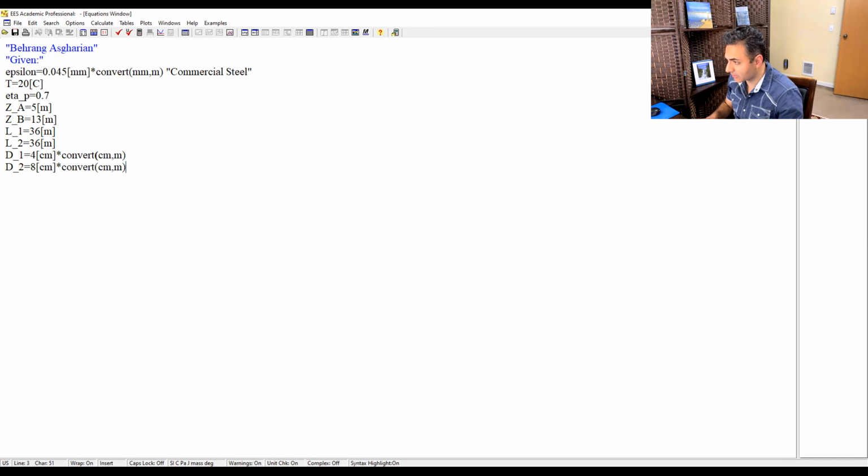Is there anything else I need to add? Yes, W dot of the pump was given also. W dot electric that goes into the pump was given as 8 kilowatts. So it's 8,000 watts. I have to use basic SI units because I told you why. You have M dot, you have HP. These are basic SI units. So because I have this, I have the basic given values.